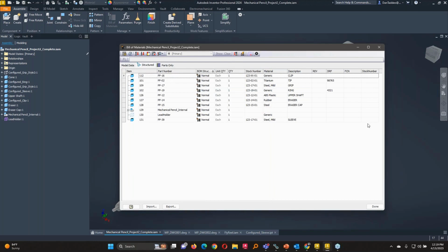Now, if you remember, Dan, you put in 1, 2, 3, 4, 5, 6. It's not listed here. Yes, you're right, because that stock number that I put in was actually for the parent assembly, nothing with these guys down here. So what I'm going to do is go to the part 39 that I just have open, which is the sleeve here. I'm going to put in 1, 2, 3, 4, 5, and let's put 0, 2. Okay, so that's my stock number. I'm very creative with this.